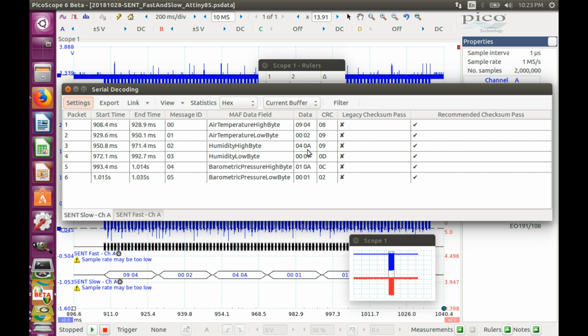So to figure out what the power supply voltage is, we need to take 1.1 volts, multiply by 1023 and then divide by the value that we observe, 330, and we are getting 3.4 volts, which is close enough.